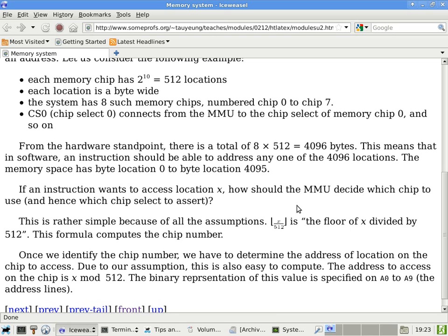Okay. Any questions at this point? Yep. I'm wondering if you only have one D set, how do you do long-term storage? Wouldn't every time you use this chip, you lose all the data you have stored on that chip? Well, okay, you're talking about the differences between DRAM versus static RAM. Is that right? We can assume that we are using static RAM at this point, so you don't need to refresh the RAM chip. I have an analogy later on that will describe exactly how a memory cycle works, so maybe that will be helpful.